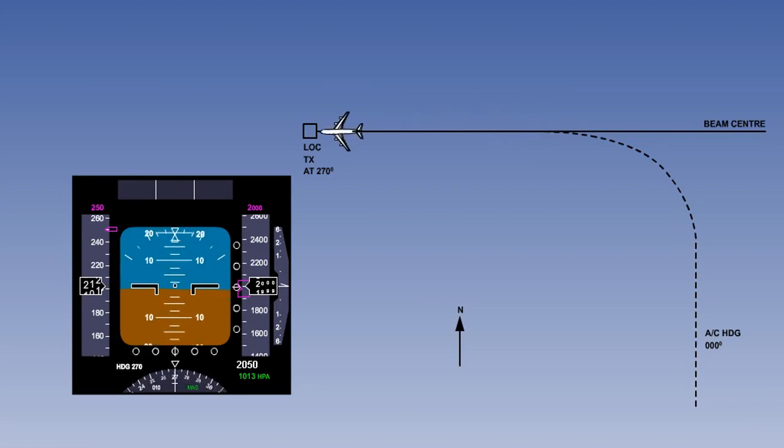the opposite side. A flight director computer takes this same raw information but processes it, working out the rate of change of deviation. This additional data allows the system to anticipate approaching the required horizontal or vertical flight path, and therefore it can adjust the amount of roll or pitch input so that the aeroplane smoothly intercepts the flight path and does not fly through it. The flight director adjusts the flight director bars, which can then either be followed by the pilot or, if engaged, the autopilot.